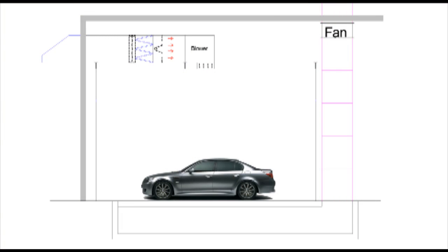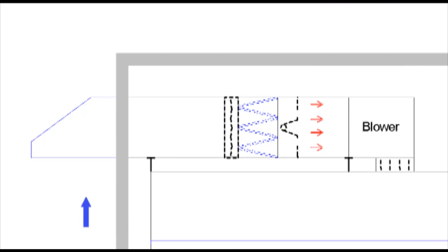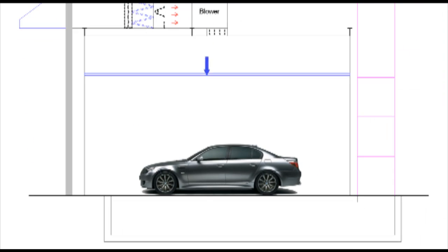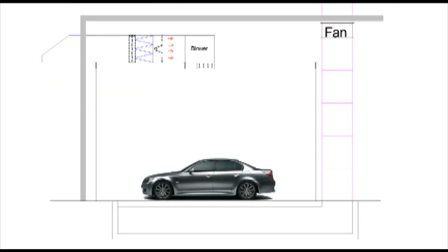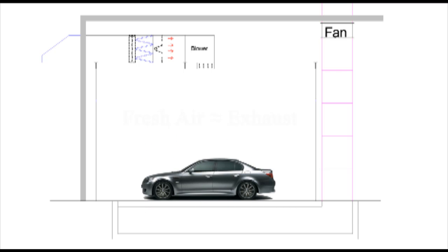Let's first start with an understanding of what an air replacement unit is and when one would be required. I've chosen the typical automotive refinish paint booth throughout this video to use as an example. The paint booth exhausts air to the outside, and that air needs to be replaced with fresh air. The fresh air is pushed into the process area where the contaminated air is pulled from at a volume equal to the exhaust. During the colder seasons, the fresh air needs to be heated.